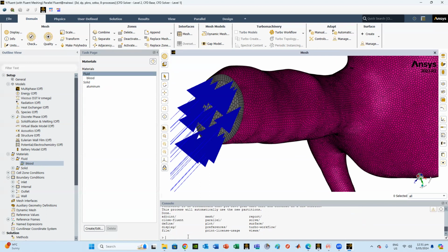So enter, and then we type file, and then read transient table. It possibly will not be accepted at first stage. So I need to as well go back to my model and change this from steady to transient analysis. But now let's see if it will pick up for me. So the name of the file will be called. So I will copy exactly what was transient. So I'm copying with the extension. That way we'll see. So it's reading for me, saying reading transient profile, and it's giving me the values for it. So that's a good sign.